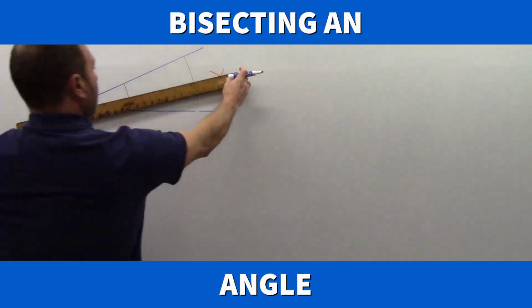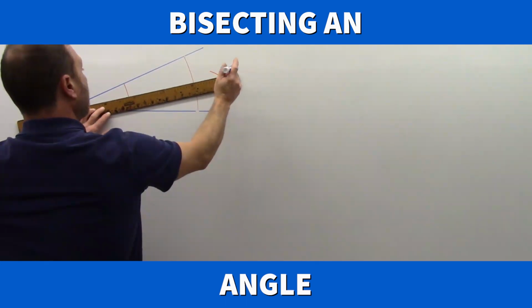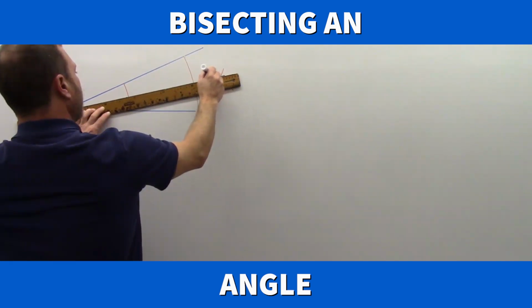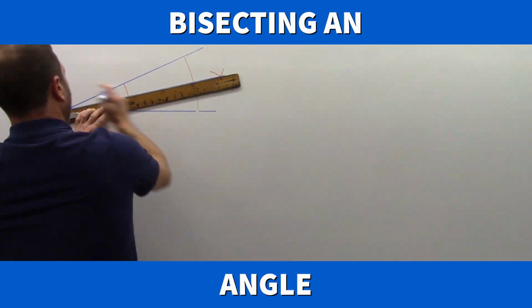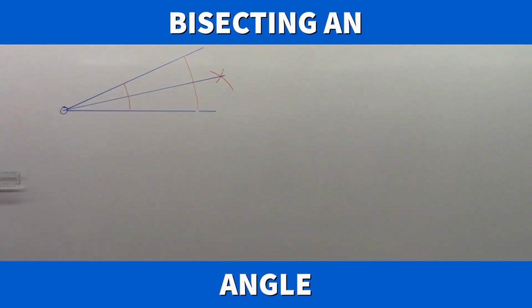And when I connect those two points, this one we're going to, what we refer to as the vertex of the angle. This is the vertex here. And now we've cut the angle in half, we've cut the arc in half. That's bisecting an angle.